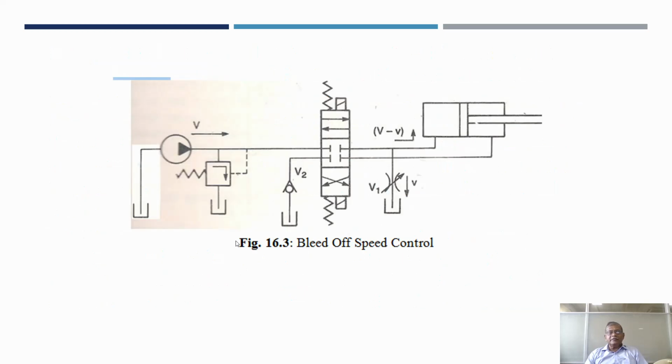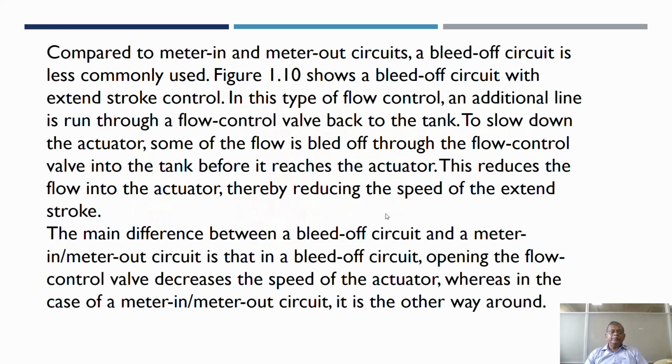Let us see the circuit. Here you can see that the pump and all these things are the same. Once the excess pressure is sensed, it will be diverted to the reservoir. Compared to meter-in and meter-out circuits, the bleed-off circuit is less commonly used.